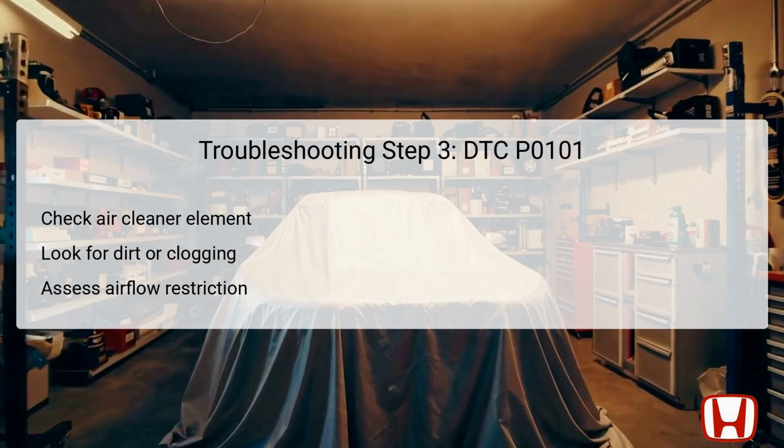The third step in diagnosing DTC P0101 involves checking the air cleaner element for cleanliness and functionality. A dirty or clogged air cleaner can severely restrict airflow, causing the MAF sensor to send inaccurate data to the ECU.